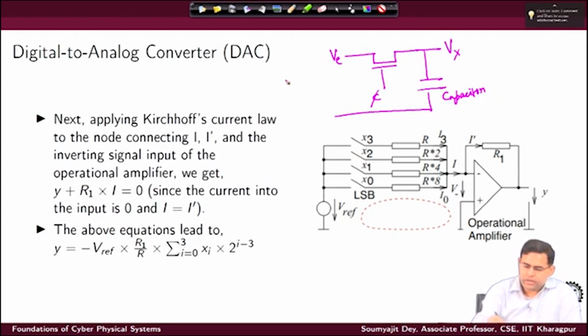So let's say here the continuous signal is coming, and there is a pass transistor here. The output goes to a capacitor, and I am actually reading the voltage across the capacitor. So now what would happen is this pass transistor is activated by a clock which is sending a positive edge at a period of H. Again at H, so let's say these positive edges will have a periodicity of H, right?